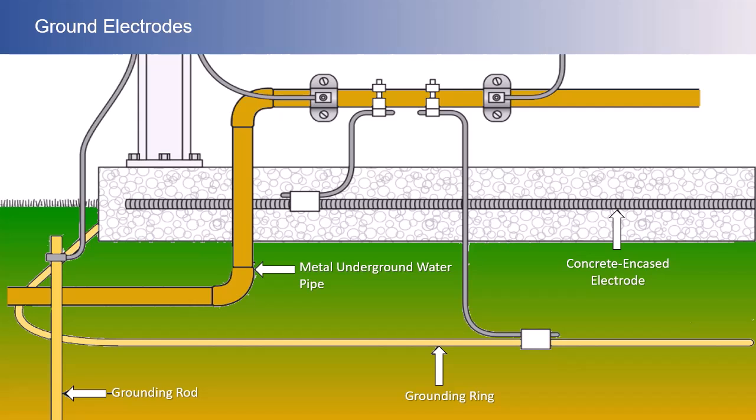steel. Electrically connecting to existing water or gas distribution systems was often considered to yield low ground resistance. However, recent design changes utilizing non-metallic pipes and insulating joints have made this method of obtaining a low resistance ground very questionable and in many instances unreliable.